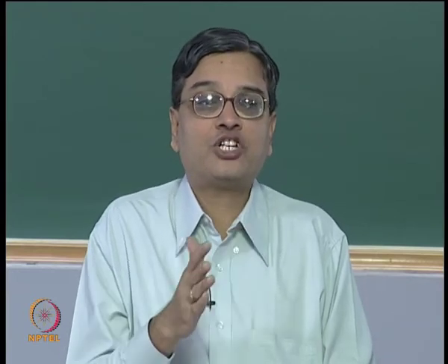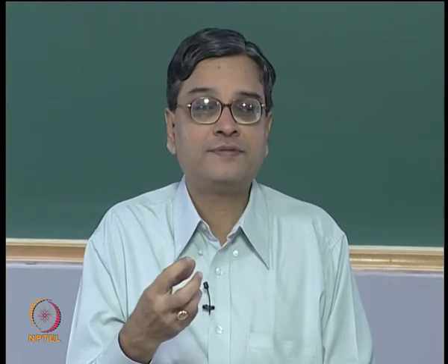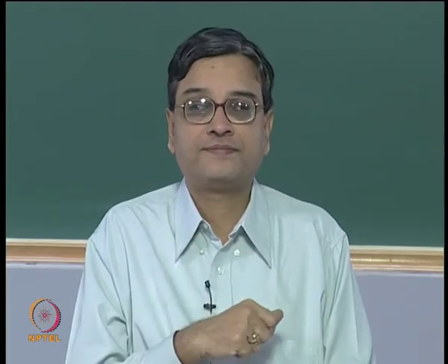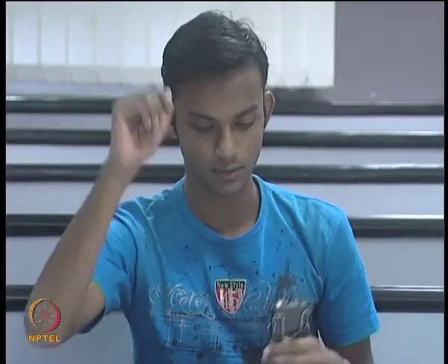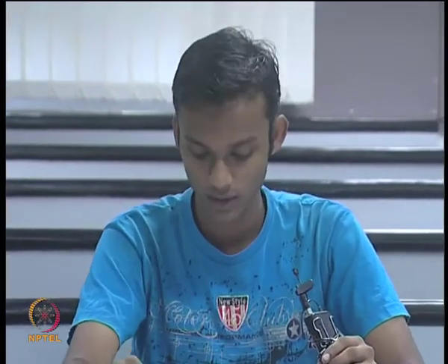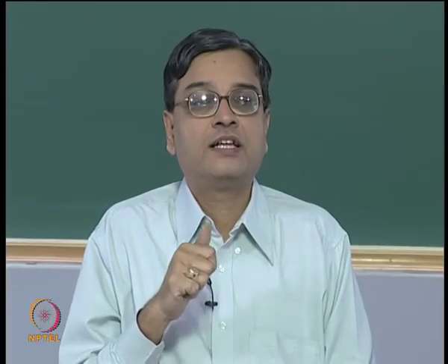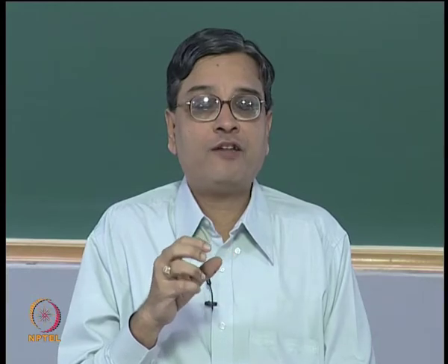So, initially to start with, they did not have an idea that it is a function of thickness. Once they understood it is a function of thickness, then you have to have a rationalization of how you should arrive at the thickness of the specimen. So, what is the relation between plastic zone size and the fracture toughness? Let me put it this way: when you have to do the fracture toughness testing, we wanted to identify what should be the size of the specimen. For the specimen thickness calculation, we have utilized the plastic zone length.